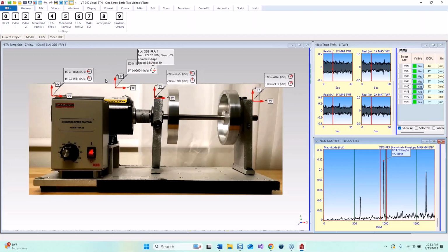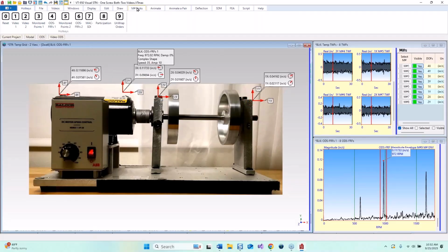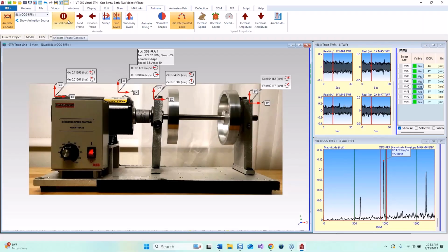but they're in units that a machinery guy would, let me just stop this so we can talk about this for a second. A machinery guy would look at this and say this vibration is 1/10 of an IPS at the running speed. That's certainly safe. When the vibration gets up to an inch per second, again, we're using English units here, that means the machine is about ready to fly apart or go through the ceiling in the building.